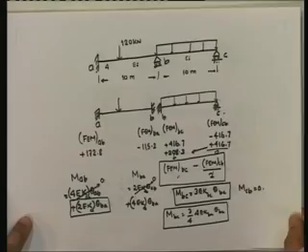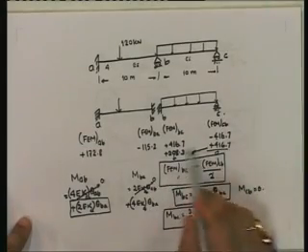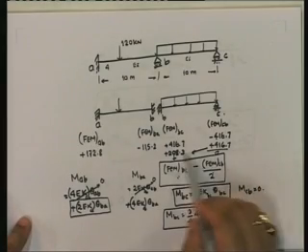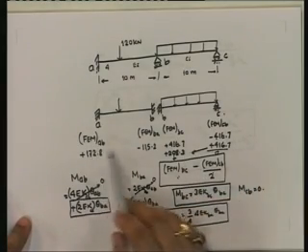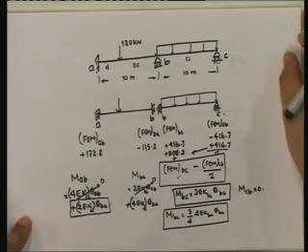So in other words, for a modified member, as far as computation of fixed end moments is concerned, we will see that this is actually incorporated into the modified stiffness. So as far as the fixed end moments are concerned, there is no difference from the original. Okay, fixed.